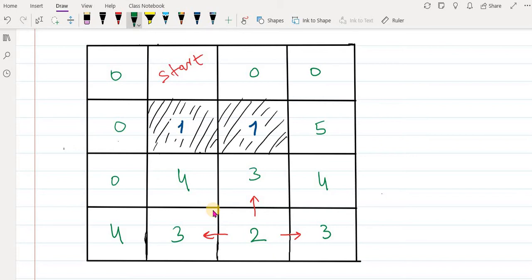Because we assume that moving from one cell to another cell, the distance between these two cells is 1, let's say 1 meter, or it costs 1 unit to move from this cell to this cell. Either this is energy, time, fuel, whatever it is. Exploring the further cells of our wavefront, if we look here, this has a neighborhood, this one also, if we come from here, this one is a neighborhood, so this one will also get the value 5.